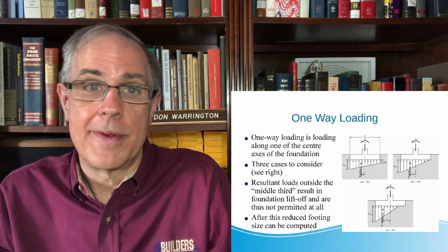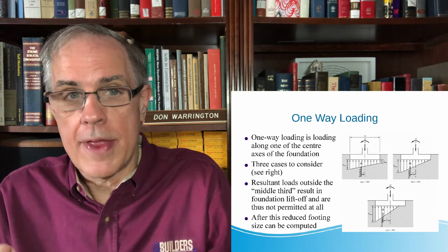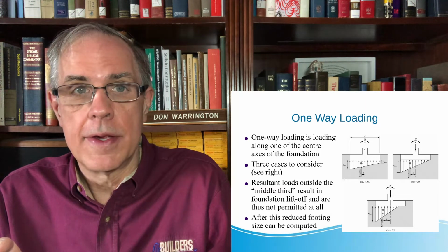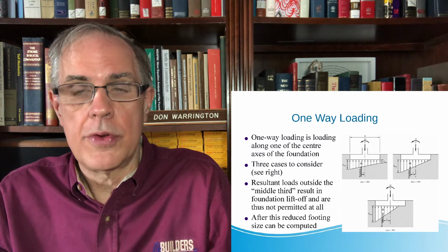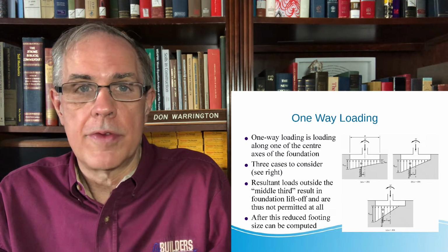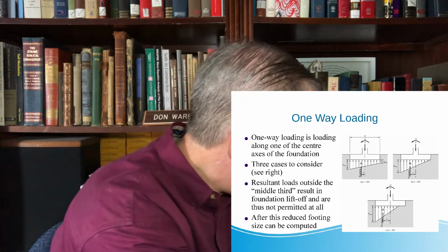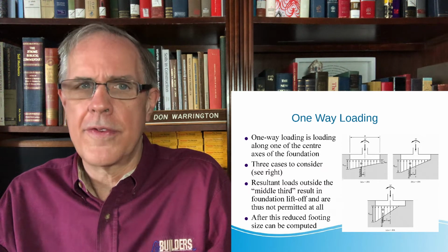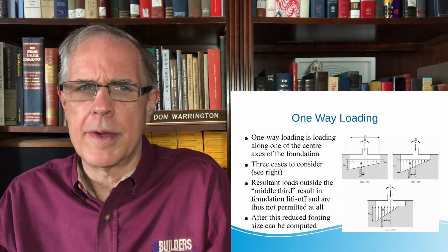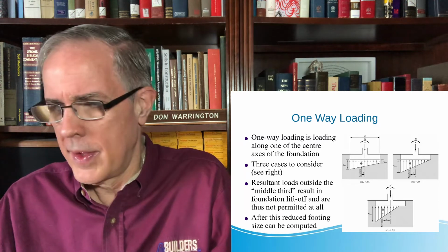Because 1/6 plus 1/6 is 1/3. So if you have that, you will have the middle third. And as long as the foundation's in the middle third, it's acceptable. If it's not, you'll get this condition. And this condition is a no-no, at least in this course. I say there's a few places you can get away with that, but not most of the time, no.